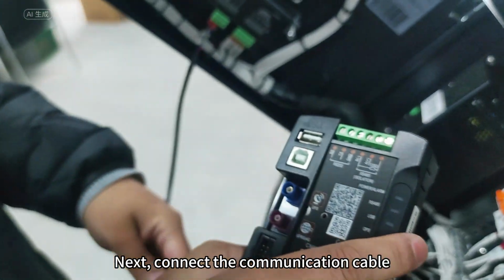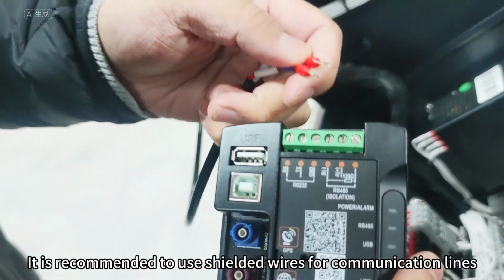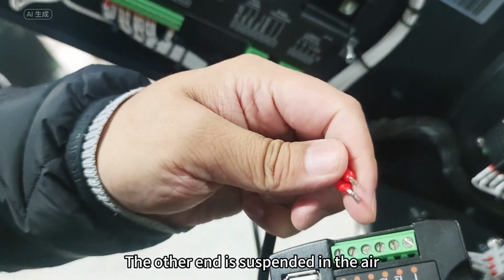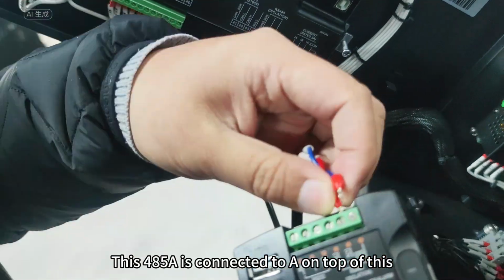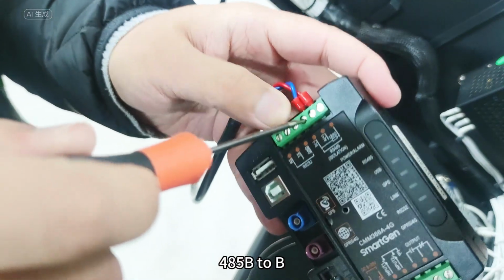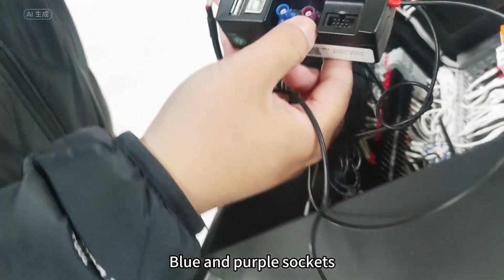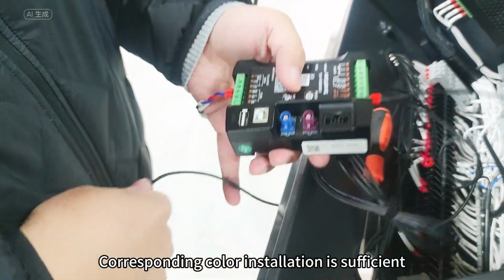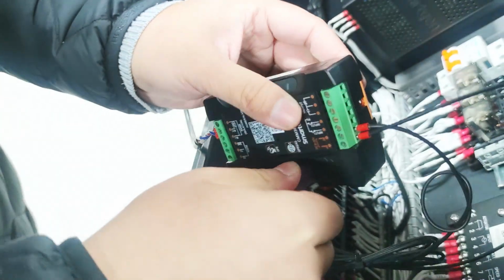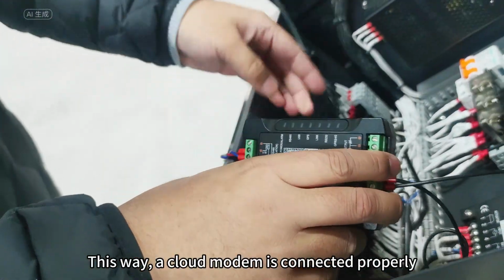Next, connect the communication cable. It is recommended to use shielded wires for communication lines. Grounding at one end, the other end is suspended in the air. This 485A is connected to A on top, and 485B to B. Next, let's install this antenna. Blue and purple sockets. Corresponding color installation is sufficient. This way, the cloud modem is connected properly.